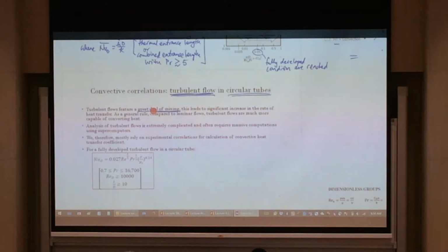And hence, whatever heated surface or colder surface, if you have turbulent flow going around the surface, it actually encourages more heat transfer. So that's why turbulent flow is a study that concerns us, because if I were to ask you how can I increase the amount of heat transfer, then the turbulent flow region would be of interest.